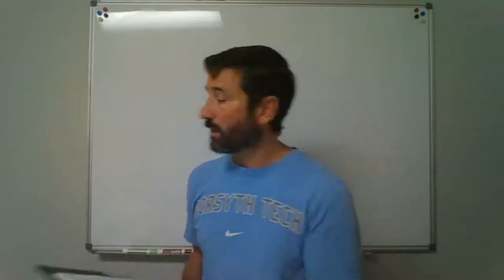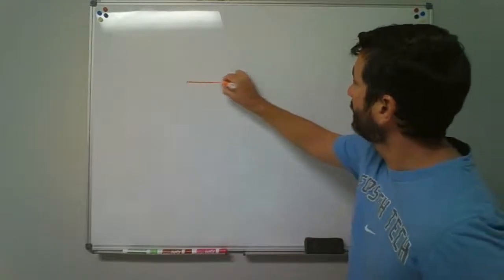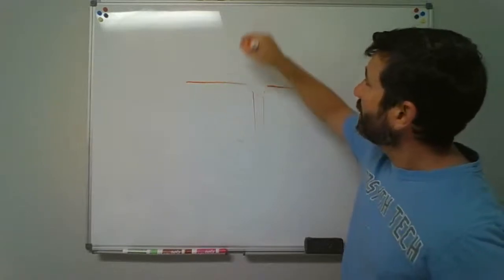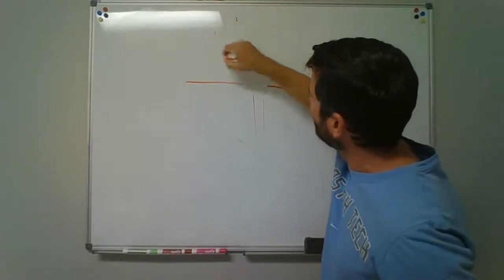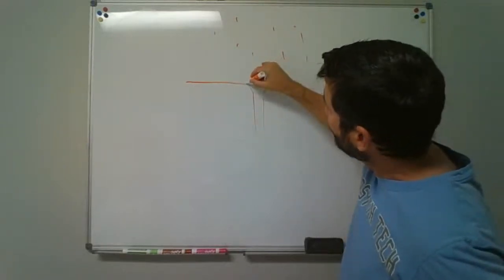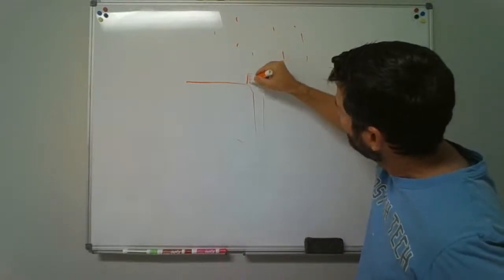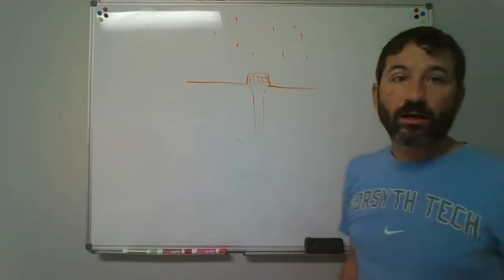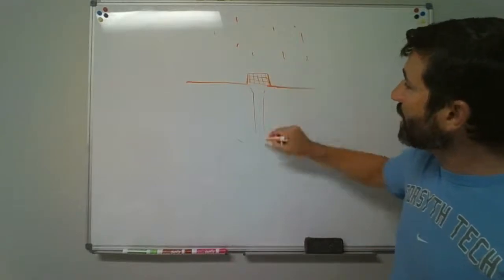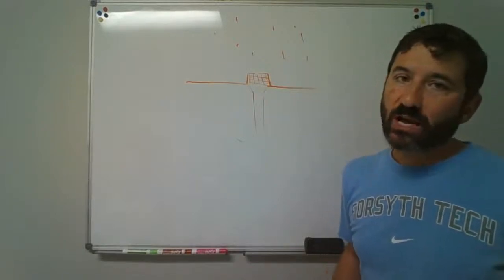Okay. So we're basically just saying if you had a roof up here and you did have a drain, that was coming off for you got rain falling on here. Okay, it's raining outside. We're going to have water that starts to build up on the roof. Now, we're going to have to put some type of strainer also over this, because what happens if you've got leaves and other debris and whatever that's going to be up here, and you want to keep that out of here, but also, you're just saying, well, why can't we just have a flat strainer across the top of it, like a shower drain or something?